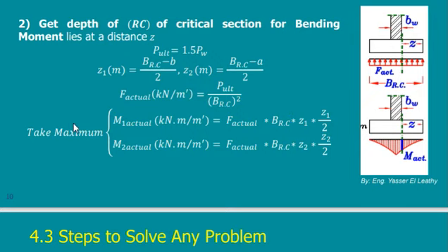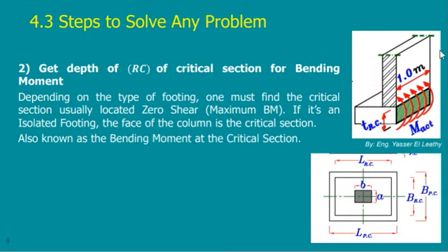Here we just calculated the moment on the footing. Once I calculate the moment on the footing, I can use this moment to design the depth of the footing and the amount of reinforcement I need.